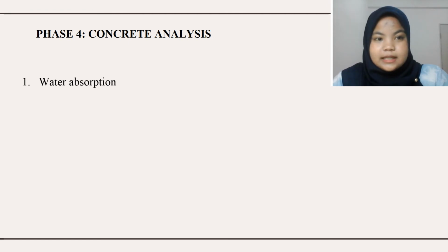Second is porosity analysis. In evaluating the deep and porous phase of concrete, vacuum saturation is a suitable method for determining the permeable porosity of concrete. In order to ensure the precision of the vacuum water absorption method, the pore structure tester is used to measure the porosity of concrete at various curing ages.